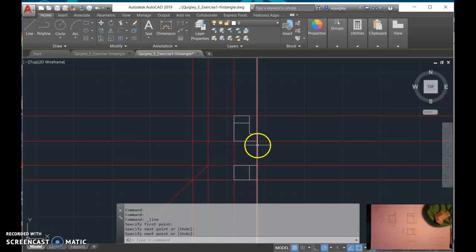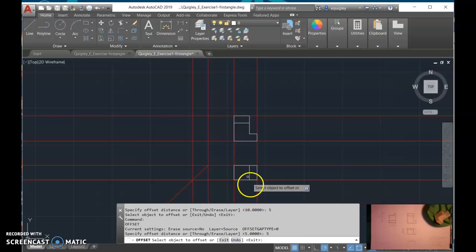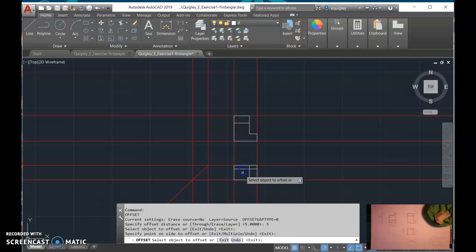Okay. And the one last thing then is the third and highest screen panel is 5 millimeters. So we could try to draw a line there, but it might be easiest to use the offset tool. Press in 5 and press enter. Start the offset tool again. 5 is the distance. So I keyed in 5 and enter, and then offset this down 5.